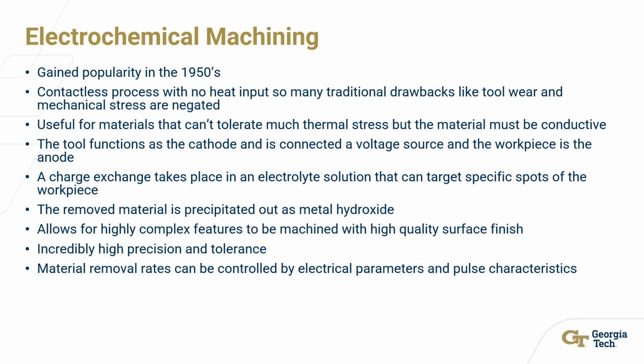So the tool functions as the cathode, and the workpiece is the anode. You plug in the tool to a constant voltage source, and then there's an electrochemical reaction with a charge exchange taking place in an electrolytic solution that can only target localized specific spots of the workpiece. Then, as a precipitate of this reaction, the material that's removed comes out as metal hydroxide.